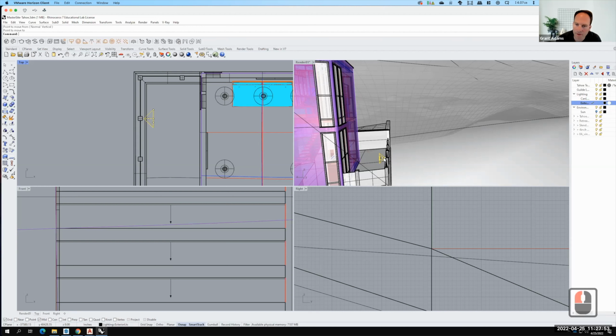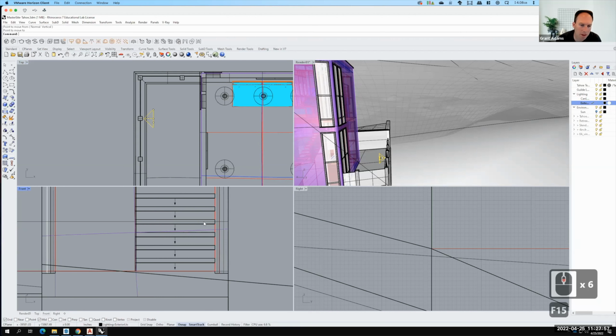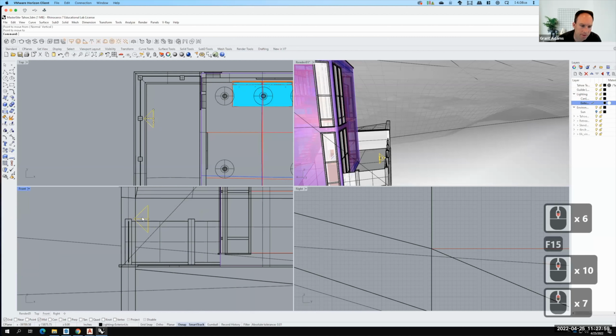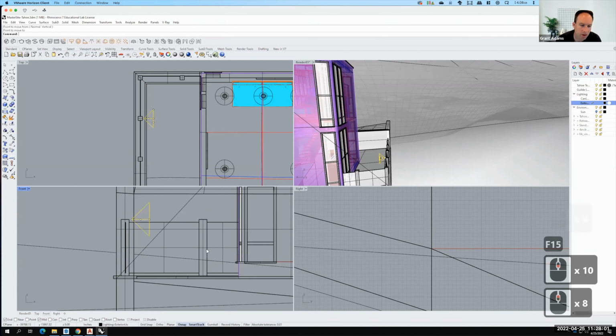inside. Now, obviously, this is pointing directly at the building, but I want to rotate it up a little bit. And I can do that in the side view here. This is also a good place where the gumball might help out. So I can turn the gumball on and I can just shift this. About like that. So now it's pointing up at the building. Maybe it needs to go a little bit higher. We may have to make some adjustments to kind of see. There it is.